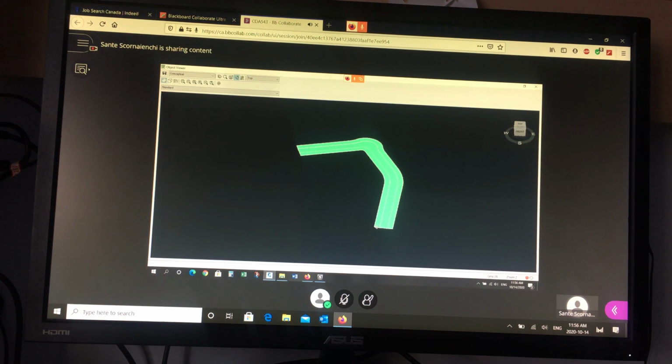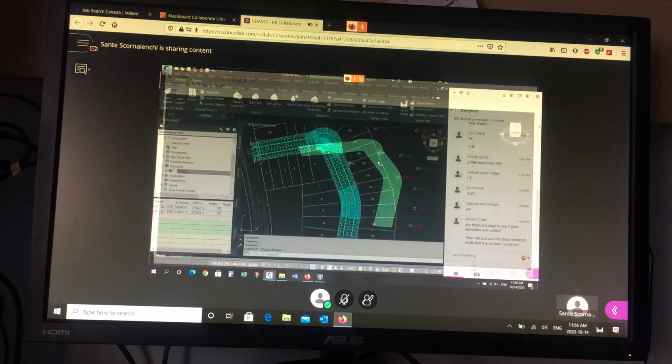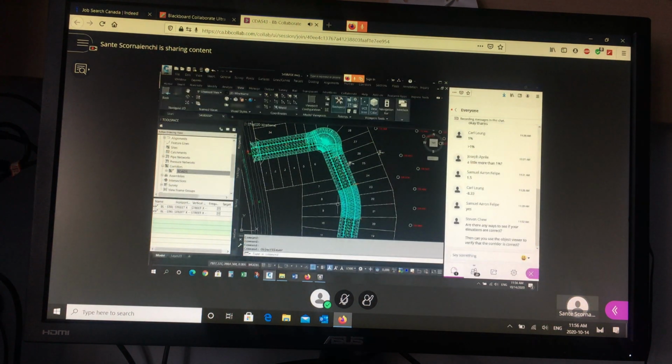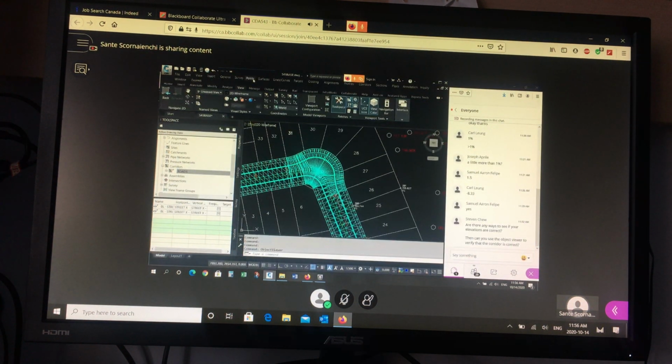If you start 0 here and go around this way, then you'll have to create the mirror of that last gutter subassembly. The intersection, leave it alone. We're not going to do anything with that. Okay? There's nothing to do there. There is, but it's not important for what we're going to use this surface for. Right? So just the elbow and the crescent is all you need to model. Okay? The last thing, and I'll demonstrate it here, if I create a point, and I put it here, end point, and the elevation is 0, right?